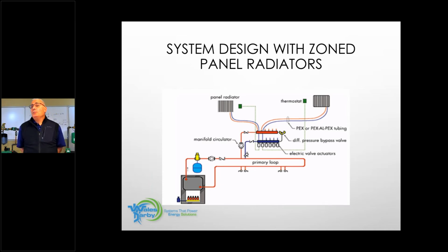These radiant manifolds, you can get them as 1-inch barrels or 1.25-inch barrels. Why not, if I have a tight space, use a radiant manifold as my distribution point? I have shutoff valves built into these radiant manifolds. I also have flow meters built into them, so I can really balance the system. And if I wanted to zone on it, I can by adding actuators. So if your mechanical room is going to get squeezed down into a really tight package, think of something like this. And then if you wanted to, you can now run PEX pipe to your baseboard or to panel radiators. Just make sure that you're sizing the PEX pipe properly. And that's also in your page 44 handout, where we show you the pressure drop per foot of PEX pipe based on size and GPM.